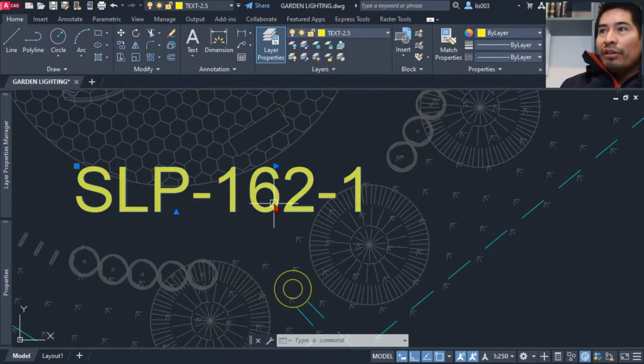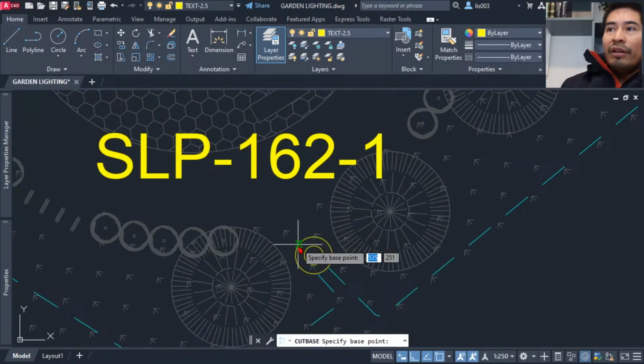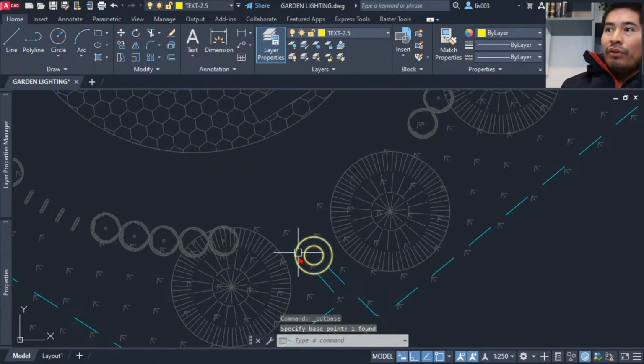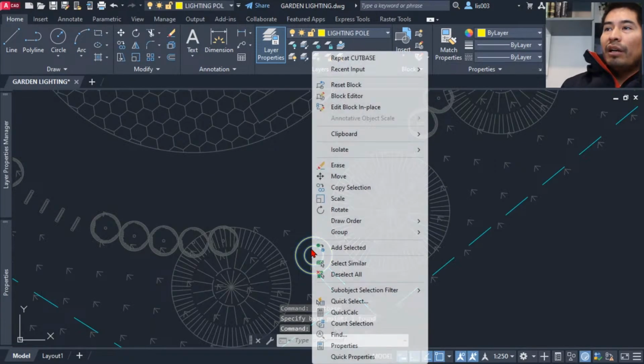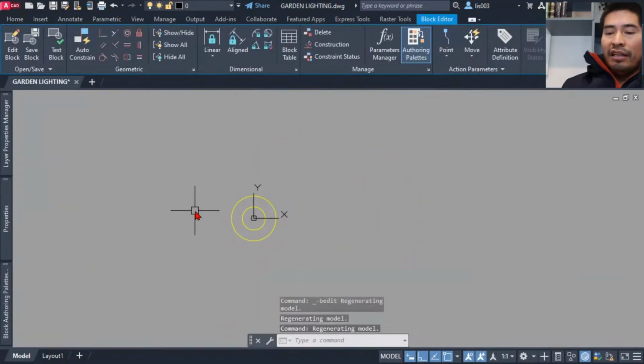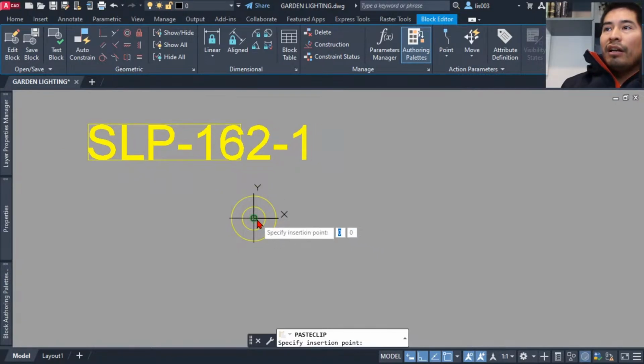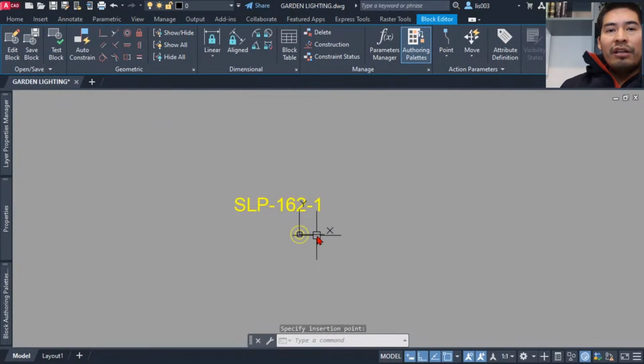So then I proceeded to copy one of his texts, and using the Control Shift X shortcut I cut it from the center point of his block, so that way when I open his block in the block editor, I could paste it with Control V. Over here I simply inserted it on the center point again, because I was trying to respect how he had this layout on his block.